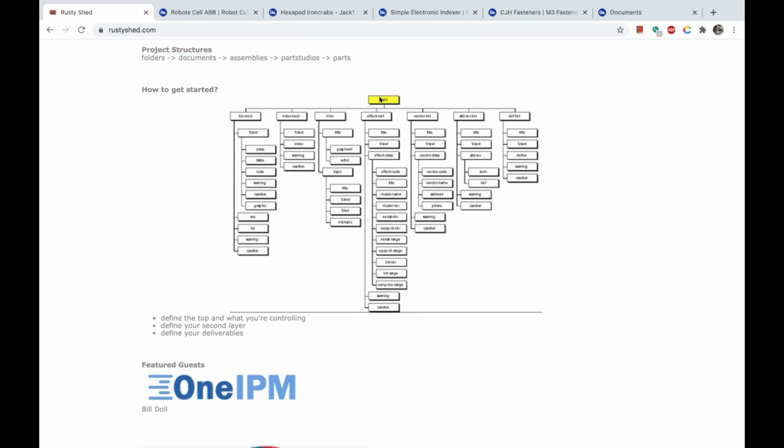Typically, I always want to think, well, what am I trying to control? If I'm making an automated work assembly line, I'm going to start with the room. The problem with the robotic cell that you just saw, where are the electronics? If you don't think the electronics is a huge cabinet full of stuff, where are you going to put that? And then the robotic cell shows up, you don't have the power there for it. And these are the things that I'm trying to control.